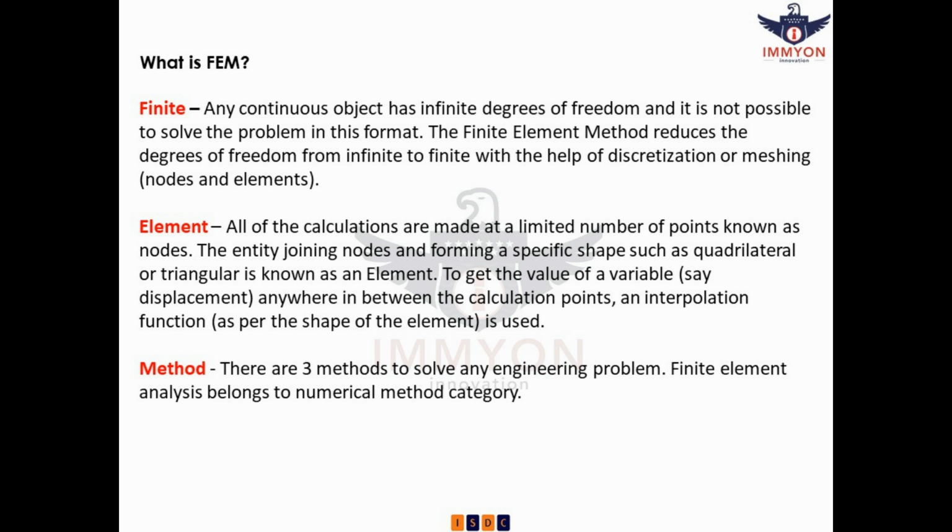So firstly, what is meant by FEM? FEM is known as finite element method. Finite means any continuous object has infinite degrees of freedom, and it is not possible to solve the problem in this format. So the finite element method reduces the degrees of freedom from infinite to finite, with the help of discretization or meshing, nodes and elements.